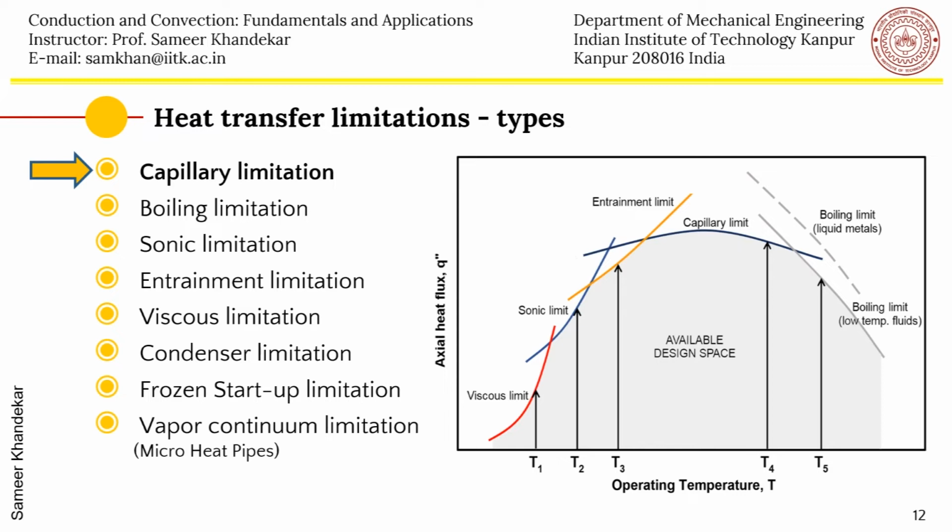As we will see, one can do a theoretical experiment in which you control the operating temperature of the heat pipe, which is usually the adiabatic temperature, by controlling the condenser cooling water temperature. That is the main way by which you can control the operating temperature. Approximately the thermal resistance will be known to you by a few experiments at that temperature, and then you can adjust the evaporator temperature accordingly.